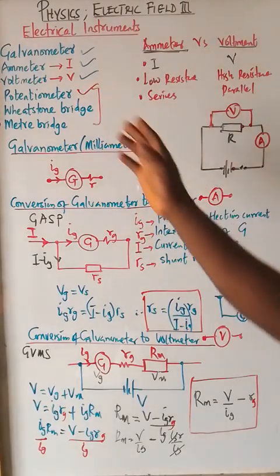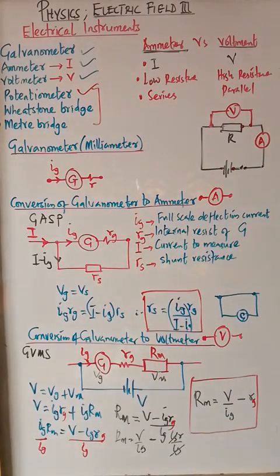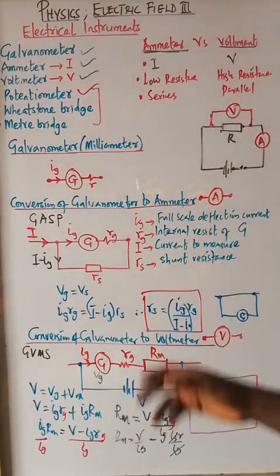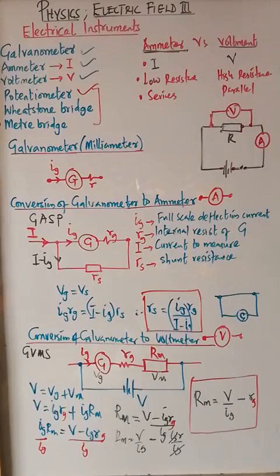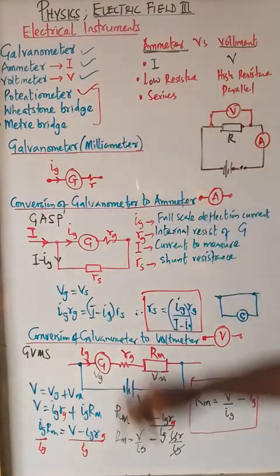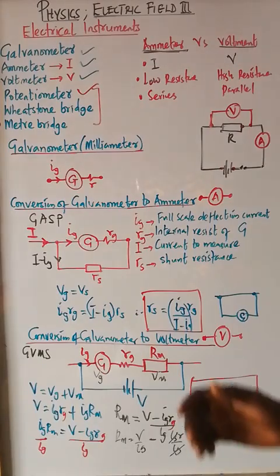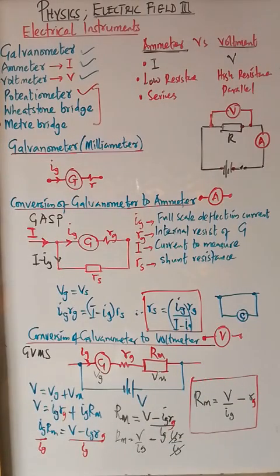It is majorly used to compare the potential difference across two cells. Let's suppose we have a cell whose PD is known, and we have another cell whose PD we don't know. So all we use is the potentiometer. So this one is also a kind of what? Voltmeter. Therefore, Wheatstone bridge and meter bridge are used mainly for resistance, to compare the resistance of what? Of two conductors.